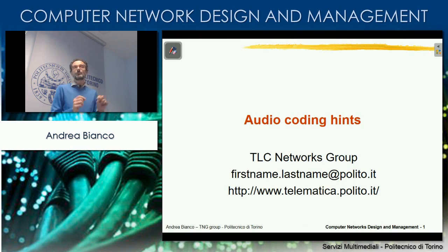The second type is instead very much oriented to the human voice generation process. You try to extract a phoneme. As a consequence, if you load the system with something which is unrelated to human voice, the coding that you get is much worse in terms of quality. In other words, the coding scheme that you are using in smartphones or in any system that wants to reduce the bit rate can be used basically only for human voice. Any other type of signal that you send is much more distorted with respect, for example, to plain PCM or anything else. Okay, that should be taken into account as well. So, for example, the background noise that you typically send over the phone, even if you don't know it, is much better represented on fixed phone lines with respect to the GSM schemes.